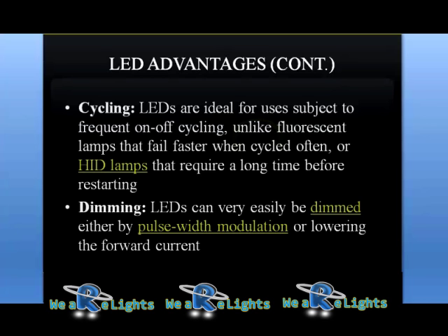This is just one of many situations where consumers mistakenly use tactics to save energy, which simply don't work. For example, some buildings unscrew a single bulb in a fixture in an attempt to lower their electricity use. What they don't know, however, is that the energy usage in a fluorescent fixture is approximately the same whether the bulbs are turned on or off. This is another anecdote you can use to persuade a building owner that their existing light systems are simply not